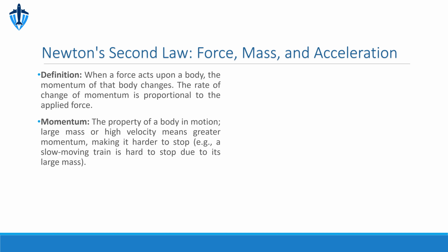Now, let's explore the fundamental principles of gears as they apply to aircraft mechanics. Gears, like those shown in the figure, essentially act as levers. We distinguish between the drive gear, which provides the input force, and the driven gear, which receives that force. In this lever analogy, the diameter of the driven gear acts as the effort arm, and the drive gear's diameter serves as the resistance arm. It's also important to remember that when 2 gears mesh directly, they will rotate in opposite directions.